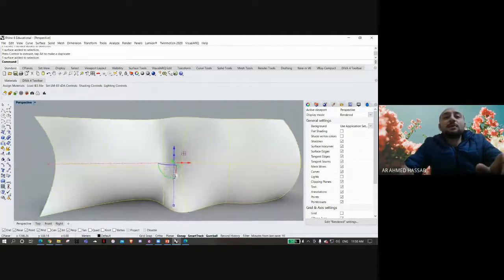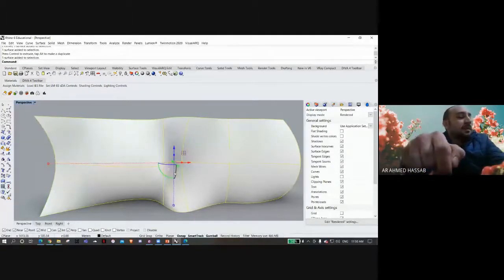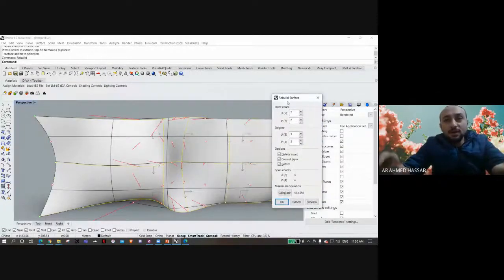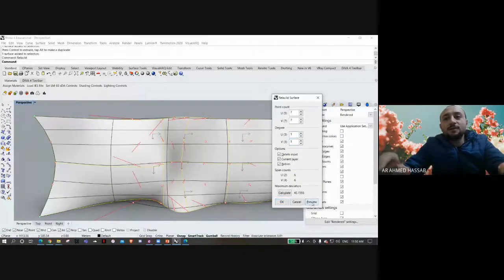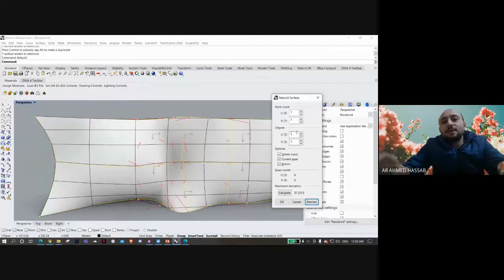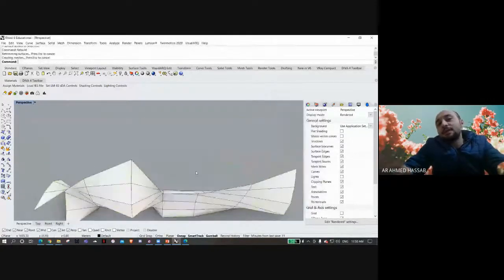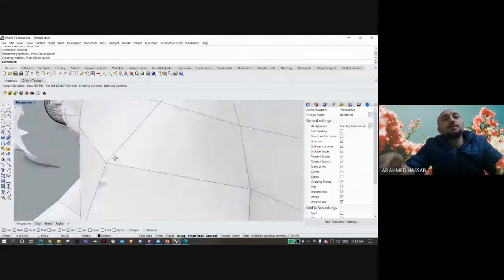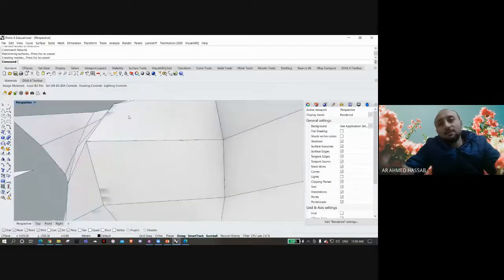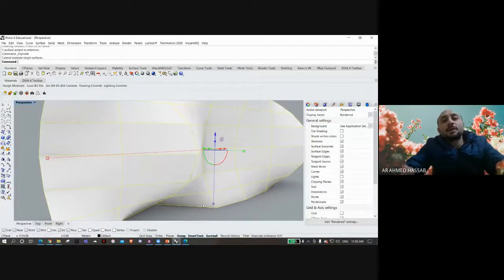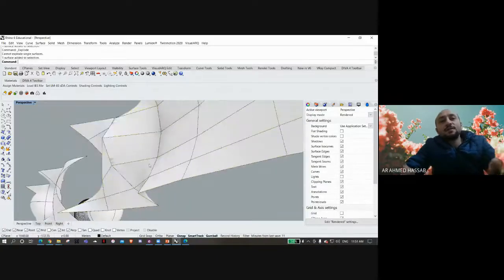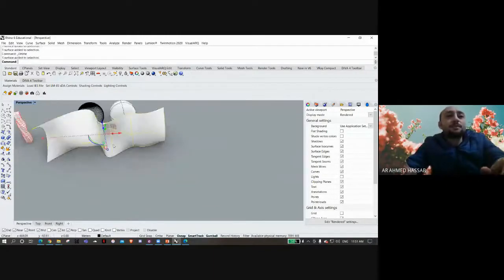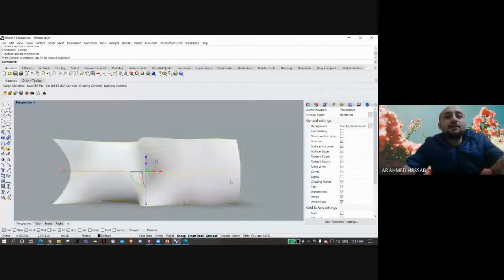And this smooth surface we can play with its degree. Because this is made in Rhino, a Rhino surface is a NURBS surface, and NURBS surface means NURBS equation. So if it is an equation, we can go inside the equation and change some of its parameters. So rather than just being a double curved surface, it can be a single curved surface, and it can be a surface of first degree. So it is a segmental surface like this, or double curved like this, and so on.